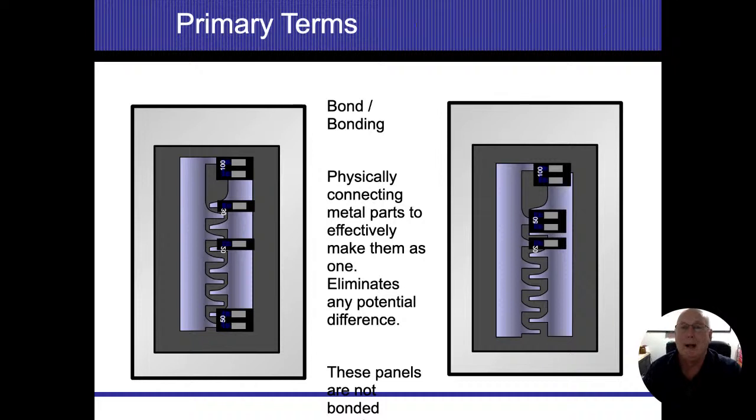So grounding does not necessarily give us that protection from ground fault. That's one I kind of want to dispel. Bonding does. Going back to bonding, item to item, it makes two things the same potential. I want you to also know what the main bond is. For most city water systems, our main bond is going to be located at the first means of disconnect. So wherever that first main panel is, the first thing I turn the power off on, that's where my bond's going to be.